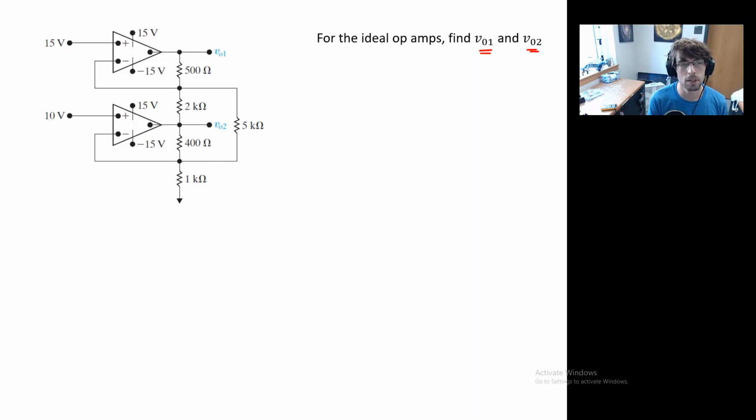I will notice that here, sometimes I've mentioned that if you have two lines that are intersecting and you don't want an electrical connection, you do this loop-de-loop over them, one over the other. If you do want an electrical connection, usually you have two lines crossing with a dot. So no electrical connection is two lines crossing without a dot, or I like it more explicitly with a loop going over. That's why you see all these dots here: they indicate an electrical connection at each of those intersection points.